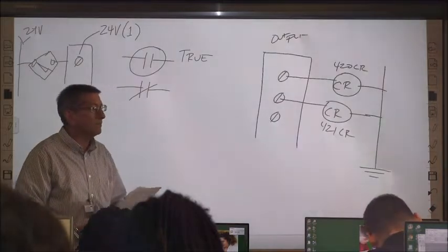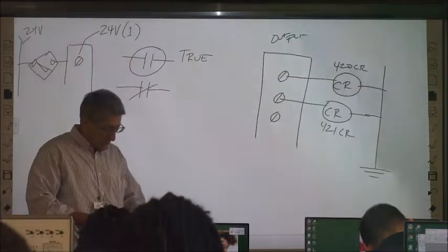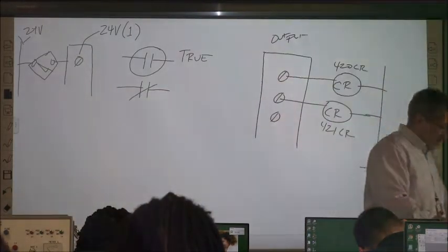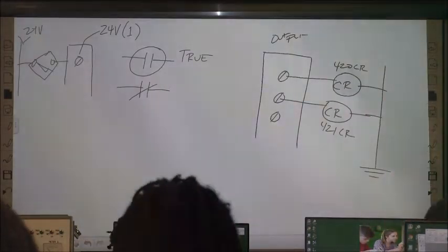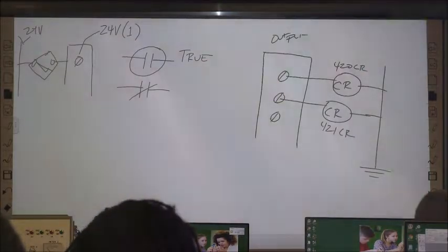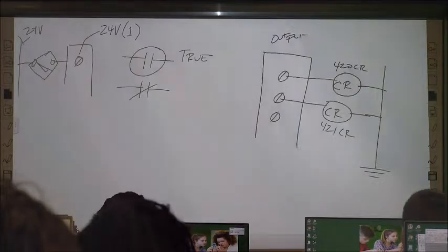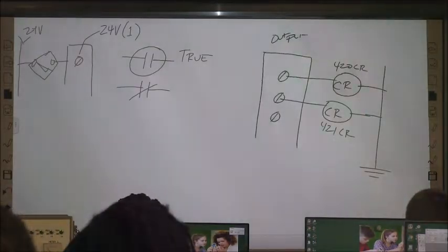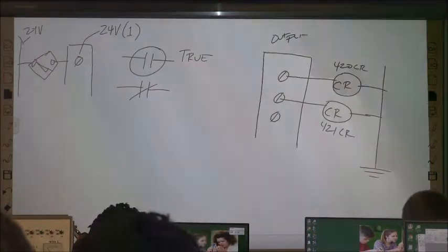What threw me were those addresses right after output, like 0172. Those are PLC addresses. That's saying that card is in slot 1, using word 7. So that's not actually an output itself. It is, yeah, that O colon 1 dot something there. See, that's what threw me, I thought it was going directly to an output device. Gotcha. And I guess another clue is it says slot 1, rack 0, group 6 on that module, right above it.